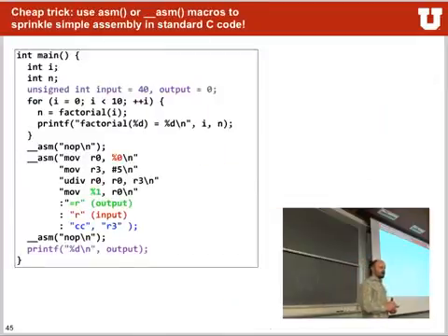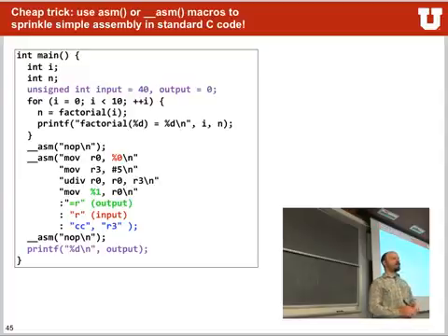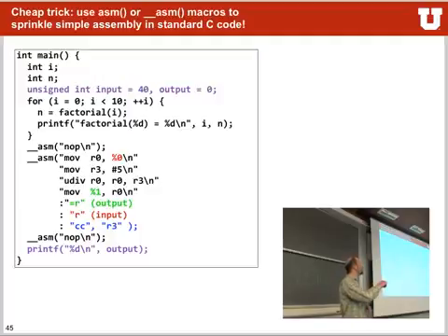And one last thing, if you really need to add assembly into your C code, there's a small little trick that you can use with the statement __asm that will execute assembly code. It's a little bit tricky how the notation is, because imagine that the problem now is you have assembly code and C code, and you have them work together. So you somehow have to tell the assembler what your input is and what you get out from your assembly code. Because in assembly, you don't have variables, really. You have registers. But in C code, you now have variables. But you don't really know where all these variables are stored at which point in time.